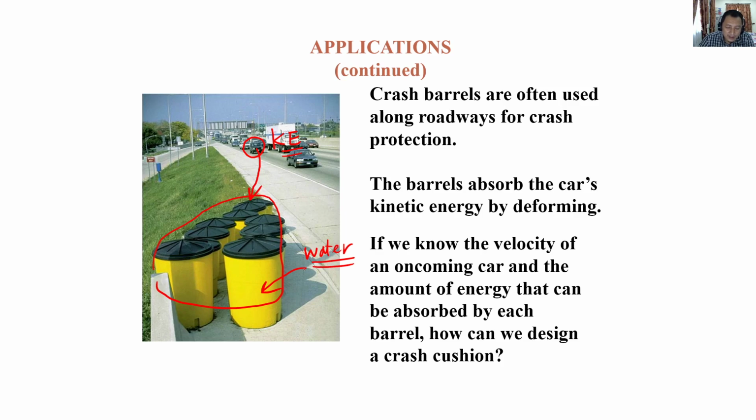So normally you will put water. So kinetic energy from the car is absorbed into all these water barrels. You can calculate how much of this car's kinetic energy, or how many water barrels you need to put here. So crash barrels are one of the ways that you can reduce the injury in the car.